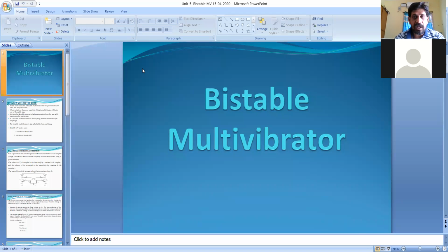That means once the power supply is switched on, the monostable multivibrator is in the stable state condition. Previously, we have seen that the collector of Q1 and base of Q2 connected through a capacitor is AC coupled, and the collector of Q2 and base of Q1 connected through a resistor is DC coupled. In this circuit, Q1 is off, Q2 is on. In the stable state condition, Q2 is on, Q1 is off.